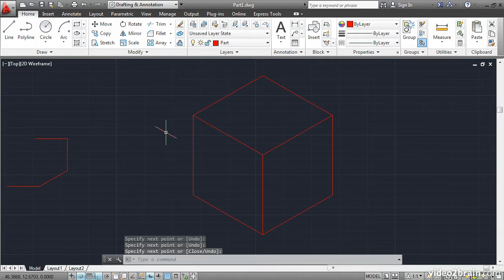So this is a 2-dimensional representation of a 3-dimensional object. You now know how to use grid and snap as aids to help you draw objects whose dimensions happen to be integer multiples of a given increment. Needless to say, not all objects in the real world are designed with integer measurements in mind, so snap has limited utility. Snap is not to be confused with object snap, which is a different concept entirely.